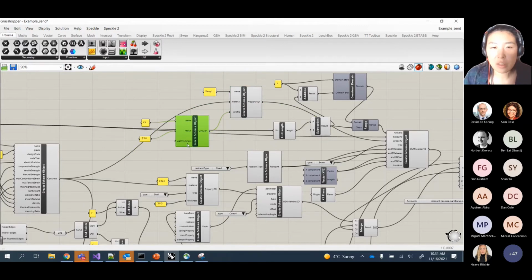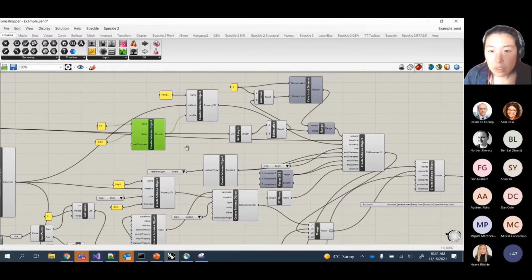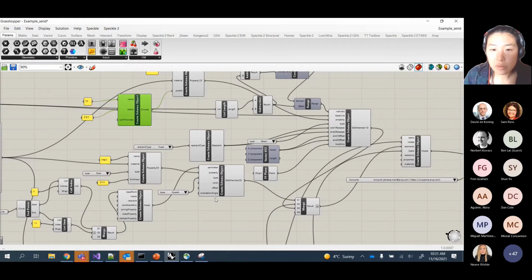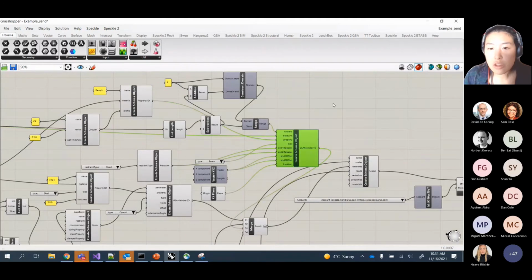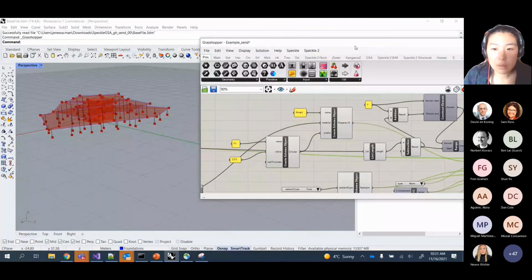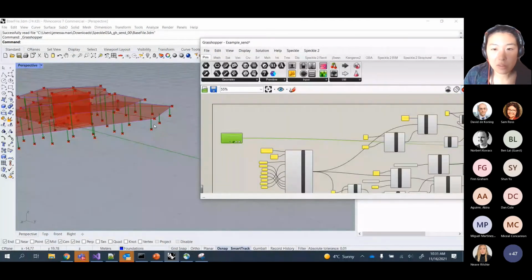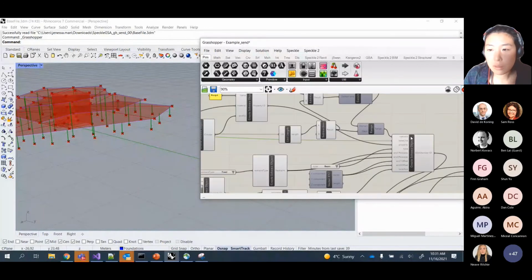We'll just make this a circular section, 250 diameter, and we'll also attach that property again to the geometry. So in this case, our baseline geometry coming from our geometry pipeline to represent these particular columns.